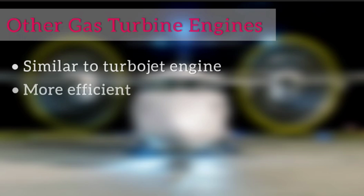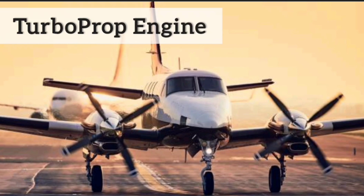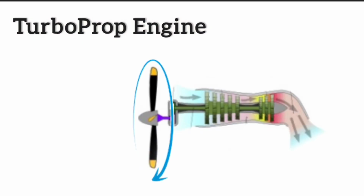The other gas turbine engines have the same working procedure with improved efficiency through their designs. So let's take a look at them. Turboprop engine. The name itself says the engine uses a propeller. A propeller is placed in front of the inlet of the engine, which is driven by the turbine shaft along with the compressor.